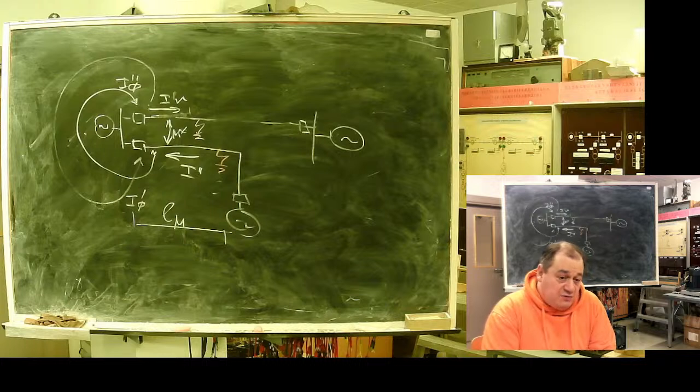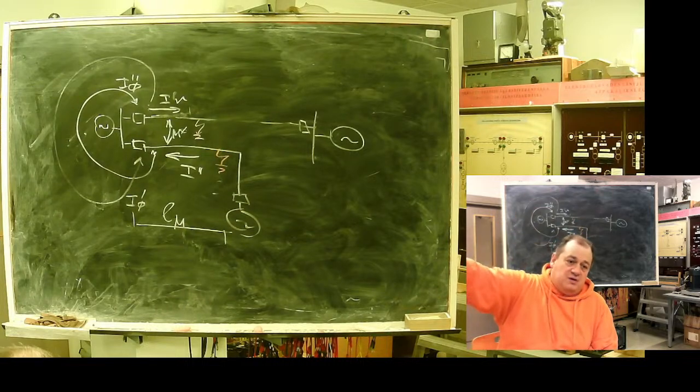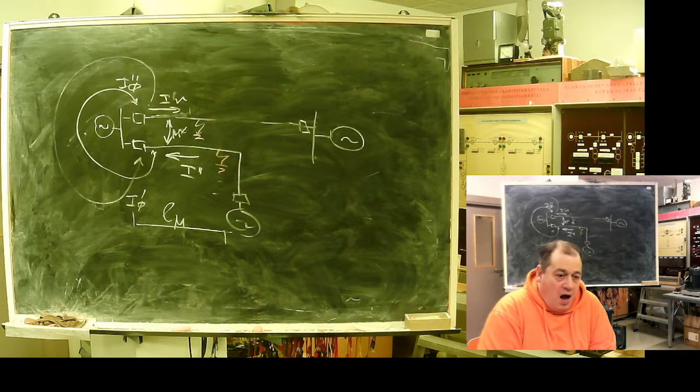with transformers. At the moment the line is energized, these transformers will develop inrush current. It starts from saturation and goes down. Inrush current is not a sine. It contains an exponential component and it contains higher harmonics.